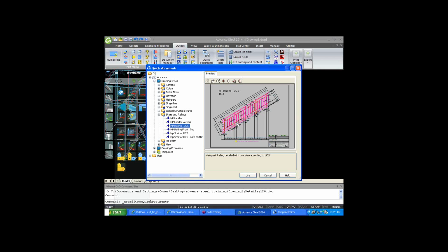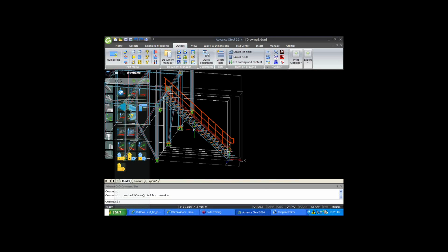Okay. No, I'm saying initially when I created the drawings, like the beams and columns... When you use the process, all main parts, because this is an assembly, should have a main part. So it will just detail the main parts only, but for the single parts, when you are using the process, it will detail them as main part and single parts.